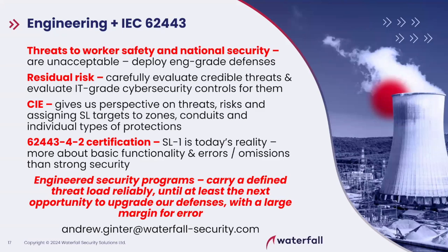We might need to do more than 62443 asks, because the threat environment is involved, because we have these new network engineering perspectives. We might be able to do a little bit less, because once we deal with the most capable threats coming across the internet, the residual risk in many places, not all places, is lower. Some places, I'm sorry, a sleeper cell of 3 spies is a credible threat. We need SL4 across the board. It depends on the site. Again, a complicated answer.